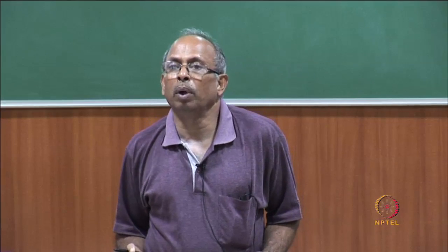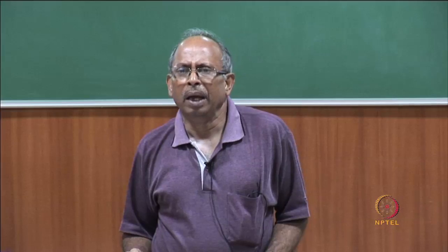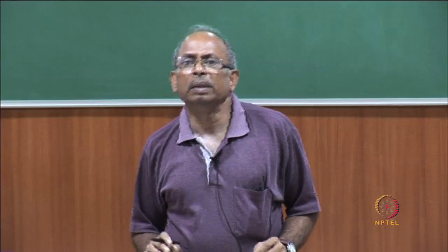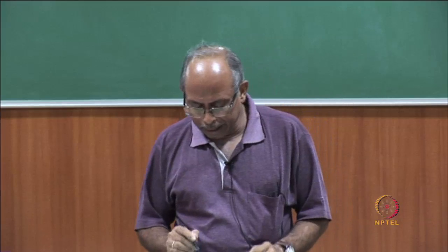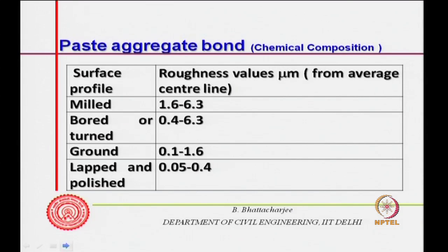So, bond length is very small. Bonded material penetrates into the roughness. Van der Waals bond can act on the surface of dissimilar material, but this does not play a major role. Aggregate-paste bond is mechanical, and this is what people studied in relation to roughness.